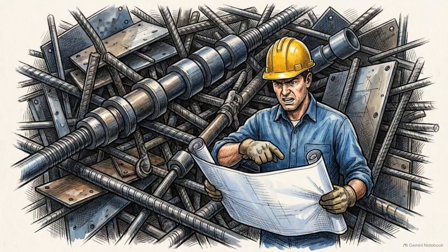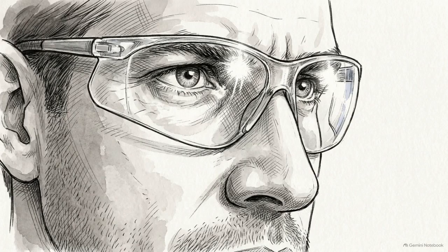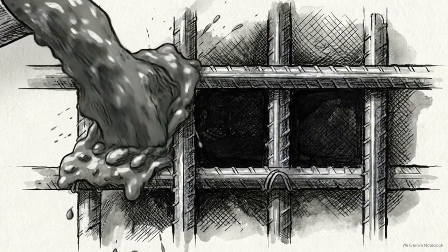Now, imagine extreme congestion at a construction joint laden with multiple steel layers and couplers. The contractor insists the layout matches the drawings exactly. In the field, the inspector's authority has limits. You aren't there to redesign the reinforcement layout. Your responsibility is to identify the placement difficulty, ensure pre-construction procedures are followed, and observe the area with extra care during shooting. Once shooting begins, active observation is critical.